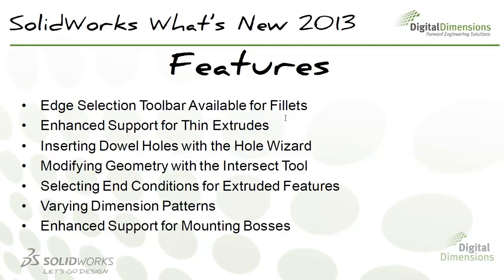Then the next thing I'm going to show you is how to select end conditions outside in the graphics area, not always having to go back to the PropertyManager. You can change the end conditions or the direction, and you can get to that same functionality in the graphics area when you edit a feature. That's available for extruded and revolved solid and surface features, and also sheet metal base flange features.